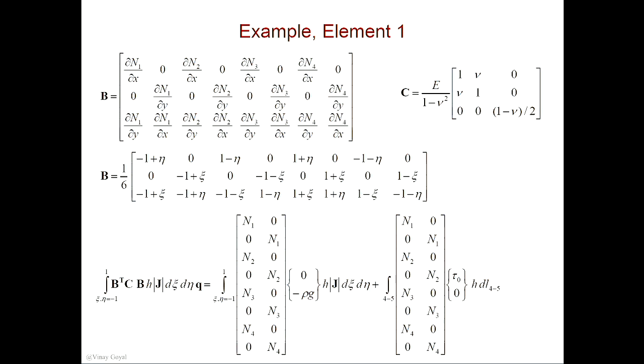Okay, so now I'm ready to calculate what bold B is. These are blocks. Remember, I call them block 1, block 2, block 3, block 4. I just expanded it out for you so you can see how it looks, and I'm putting in the values I calculated on the previous page. So the C matrix is fully known. I know it's aluminum, so it's 10E6 psi, or 10 Msi. Poisson ratio is close to 0.3.